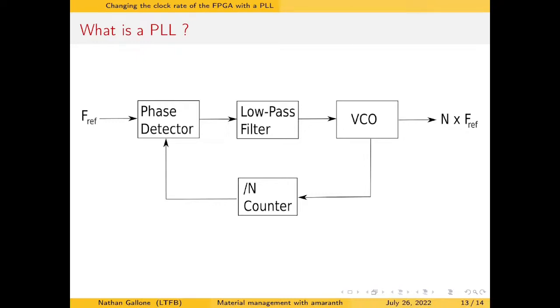of a voltage-controlled oscillator here. We then use this VCO output both as the output signal and as a retroactive information that is serving our PLL. You see there and there that within the PLL we operate a multiplication and a division. These are the parameters we control to choose what frequency to output. You'll have the occasion to see what it looks like in Amaranth within the next minutes.